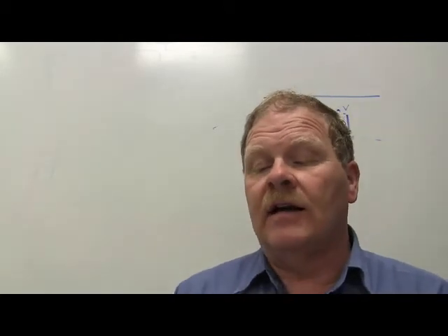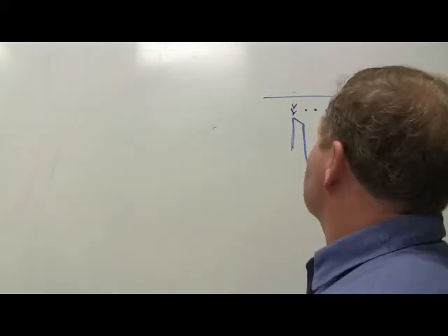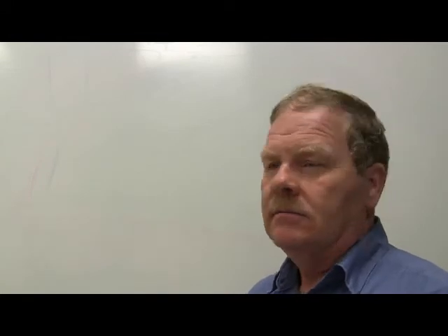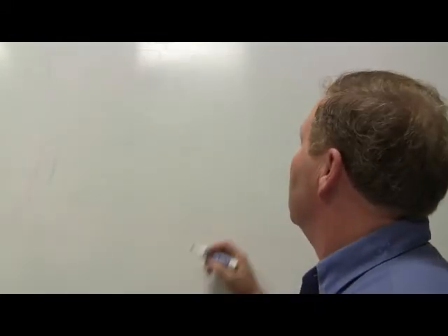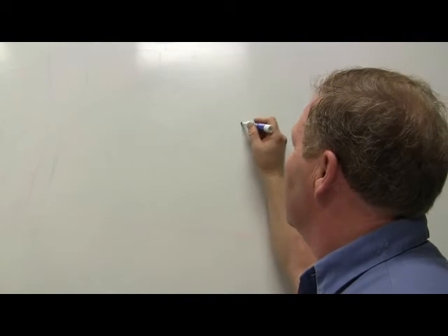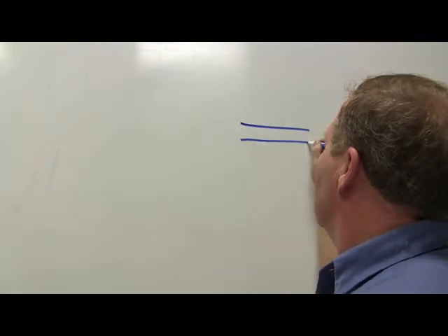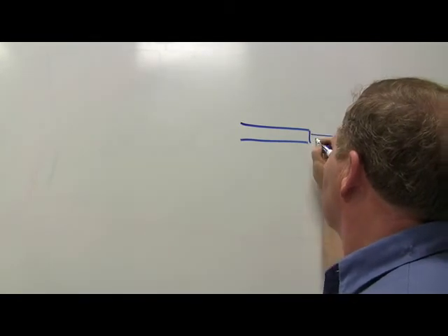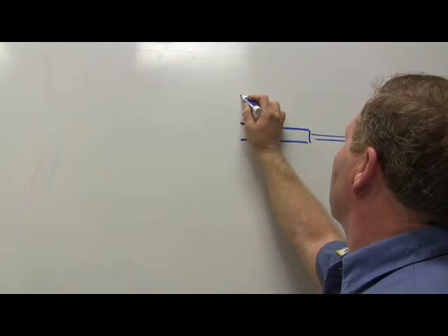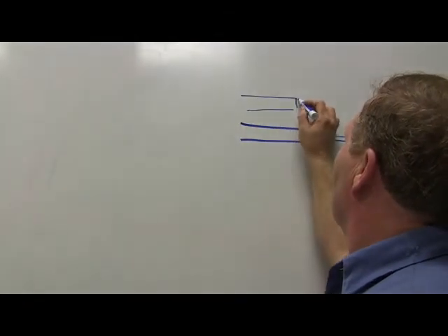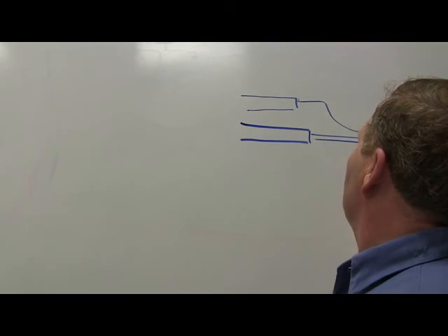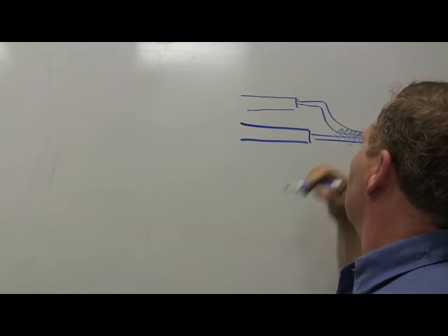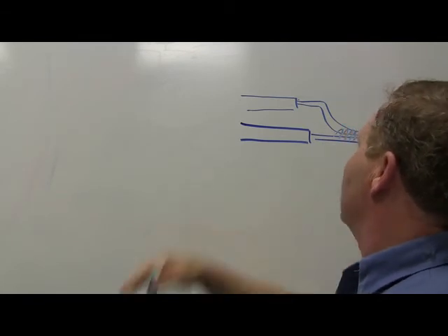Now, I will tell you one of the things that I always didn't understand. When I fix a wire, I like to solder it. Daniel likes to solder too, by the way. But sometimes from your manufacturer, they will send you a set of instructions and they'll tell you to strip your wire really long like this, and then strip your other wire really long and twist them together. Just twist them together and then put a piece of shrink tubing over it.